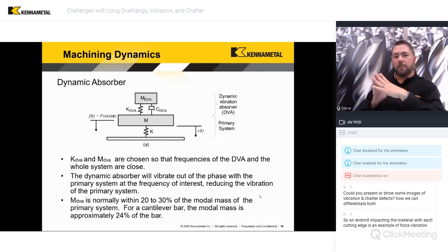So we're looking at the mass of the system, and possibly different masses that we'll get into. If we have different masses and those masses can move relative to each other, then we have to start to treat them differently. That's what we see a little bit here in this picture, where we have two masses. We also have the static stiffness, so essentially the system of springs or elastic elements. And then we have damping and damping elements.